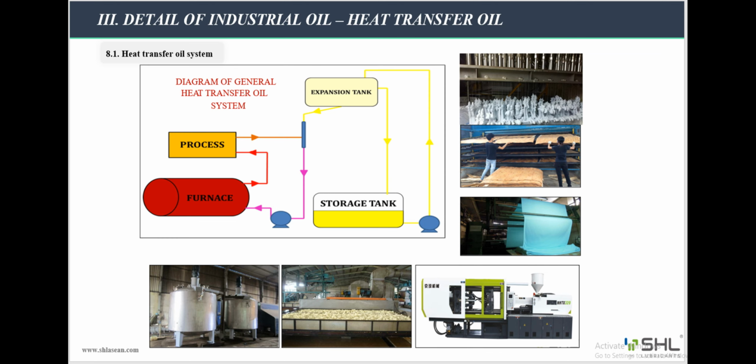So the oil will then be passed through an expansion tank containing the increased volume of oil when heated, because if the volume of the pipe is constant, the increased oil accumulation can rupture pipes and equipment due to excessive pressure in the closed system. Hot oil spills into an open system. Finally, an expansion oil tank is placed on the top of the system, returning the oil to the storage tank when the temperature drops according to the free flow principle.